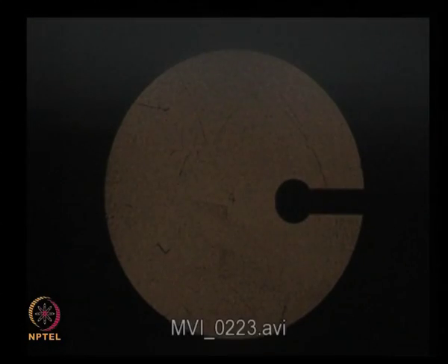Now I will go to the next case where I have roughly a spherical body sitting in that same tunnel, okay. Again we are starting the flow, you can see the vibration of this body, the flow is starting. So let us say it is forming anyway. When the flow field forms here, you are seeing that the body has an optical illusion, it looks more flat. That is an optical illusion because of the density gradient in that region. Light bends in a density gradient.